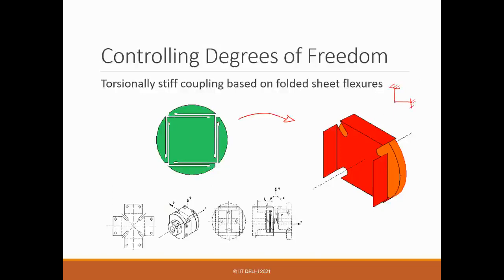So you see these are the folds, and where are the two sections? You see this is one section and another is this section. You cut the groove, right? And this is the clamp. So a very nice design, very creative, I would say. It's just made of one sheet metal again. You can see here the first part, and you just cut it and then bend it. One side bends in this direction, the other side bends in the other direction. So you can see these bends, right?